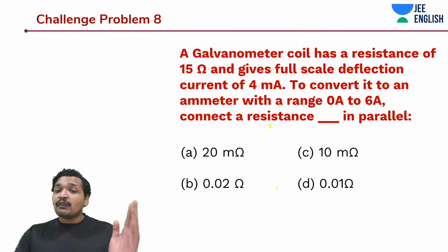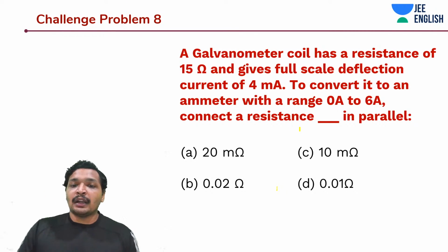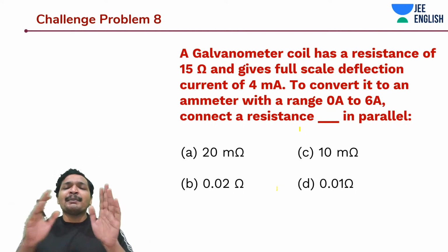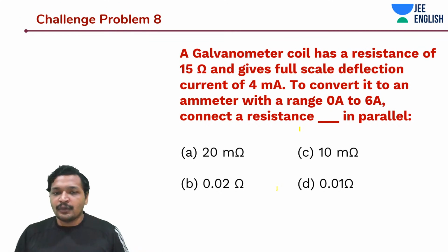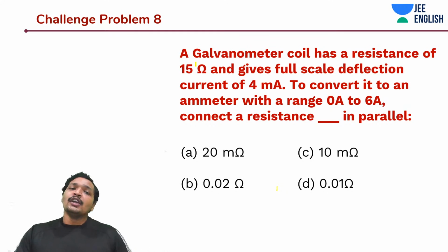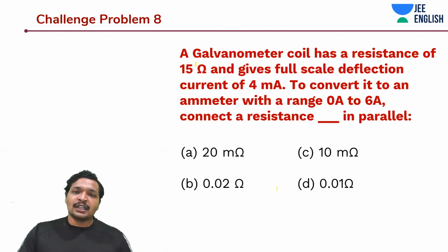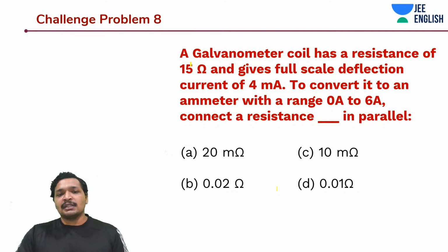You need to understand galvanometer concepts to get into even the potentiometer. The potentiometer requires the galvanometer concept, not necessarily the ammeter concept. An ammeter is placed in series to measure current, and a voltmeter is placed in, I'll come to that. A galvanometer measures small currents, and an ammeter measures larger currents. You shunt a galvanometer to measure larger currents, because if you put a very small shunt resistance in parallel to a galvanometer, most of the current will flow through it.